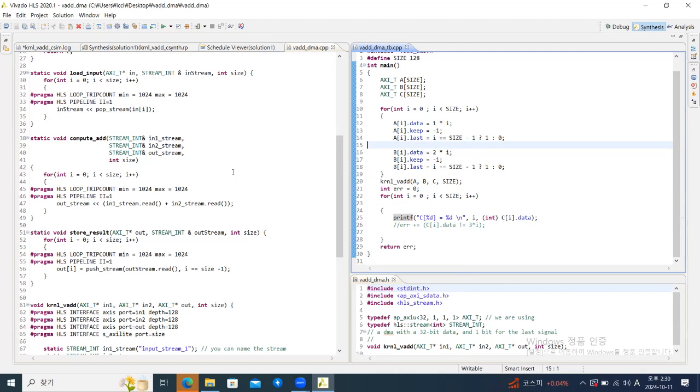Do you get it? So you see, the input DMA, the adder and the output DMA do not explicitly communicate with each other about reading and writing, right? Yes. You just wait. That's automatically synthesized by HLS. You can, however, explicitly add a FIFO IP using the block diagram.